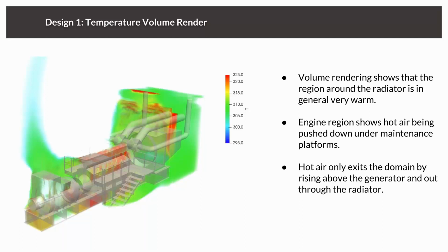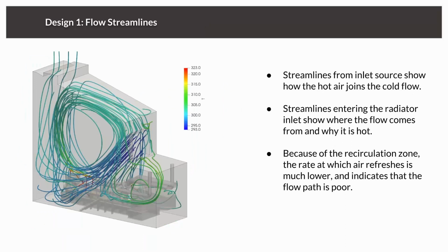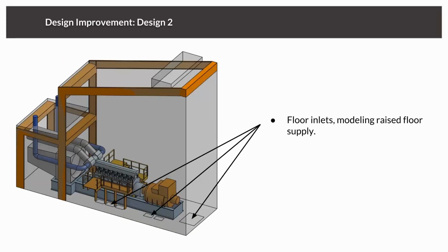There is a plume that comes on the left side, on the far side, next to and above the generator, and is being taken away by the big vortex, but on the other hand, most of the air is taken into the radiator and decreases the efficiency of the device itself. We can see a little more by visualizing the streamlines around the device. So again, a big vortex, the air is being recirculated around the radiator and it's being sucked into the device.